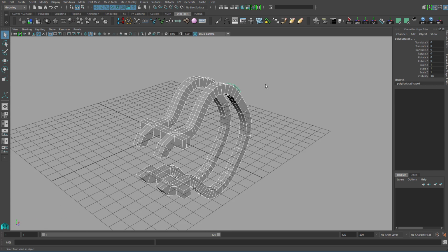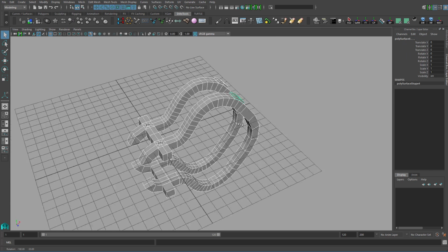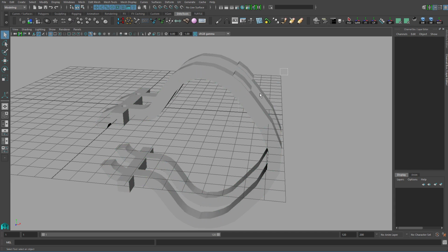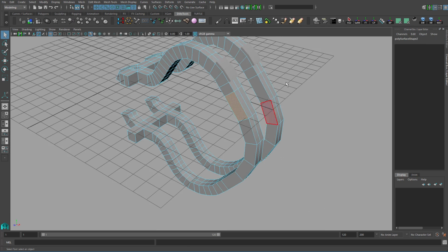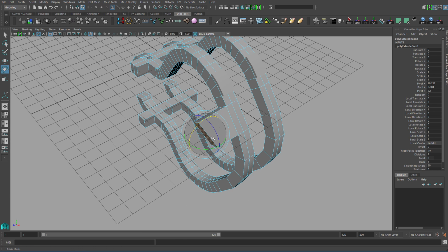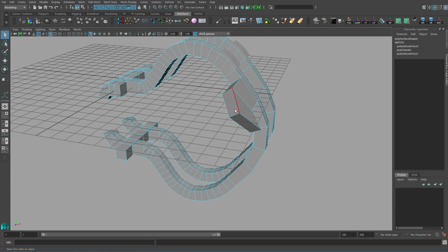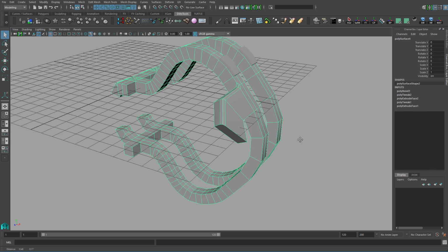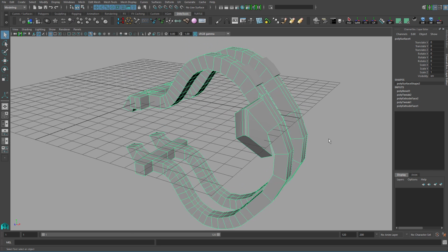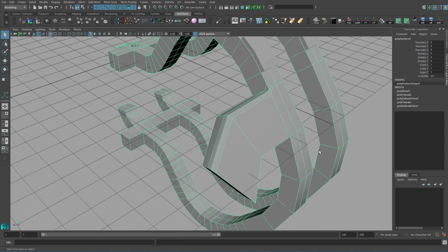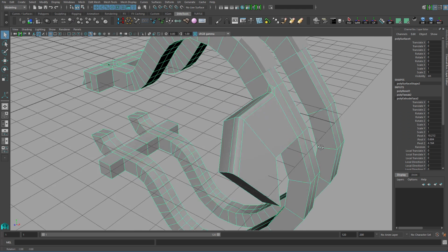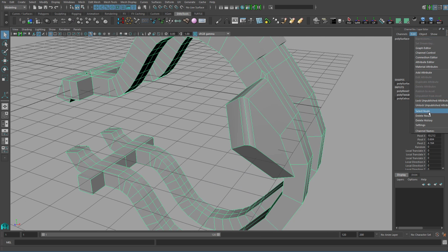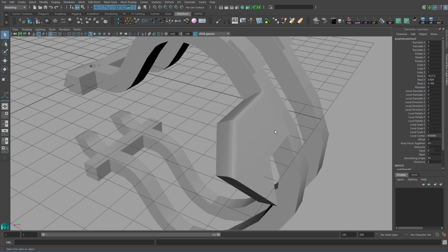One more thing I think you guys need to keep doing is delete history. When you are modeling something like extrusion and do all kinds of stuff, you end up with a lot of commands. If you did a bevel here or something, you end up with a lot of command list in the input. You can hold down Alt, Shift, and D three buttons together to delete the history. If you don't want part of it, like I don't like this extrude I did, you can grab it and go to edit and then delete node. That will destroy the extrusion.